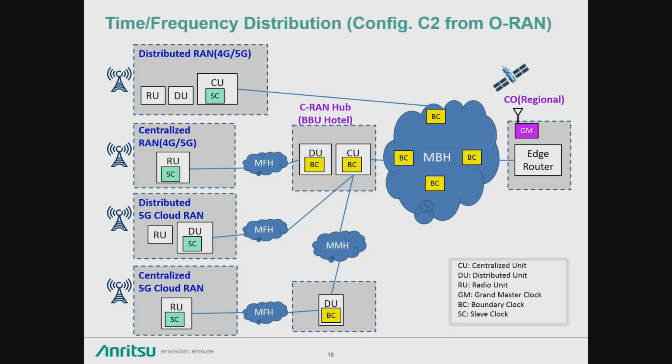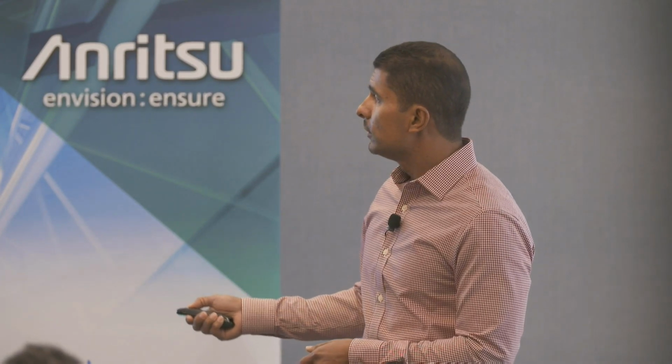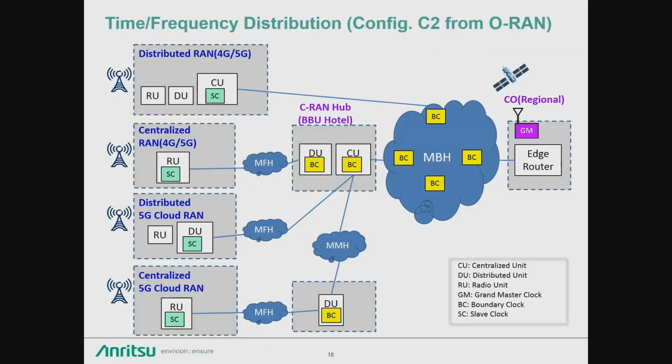This is important because, again, this is what's receiving the timing all the way back here from the grandmaster. Now, what are the benefits of this? First of which, you have one grandmaster distributing the timing, all sharing the same timing source. You also have boundary clocks throughout the network that are constantly being retimed. So you're able to provide resiliency. You can also provide multiple redundancy paths. In the event that you have something fail, you have additional boundary clocks to help support that.